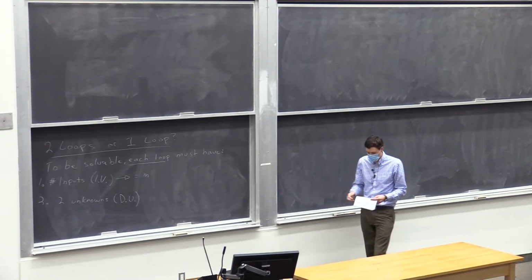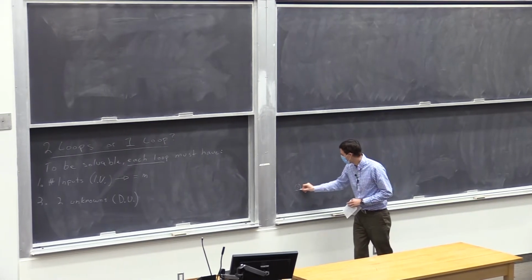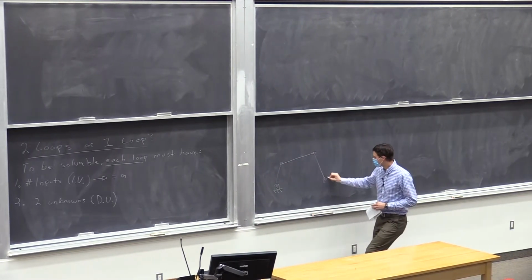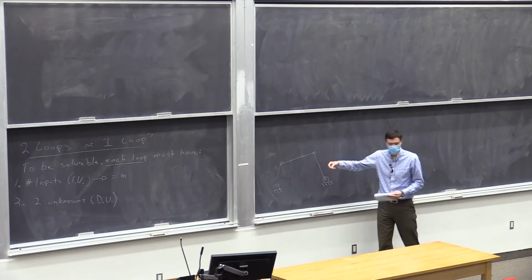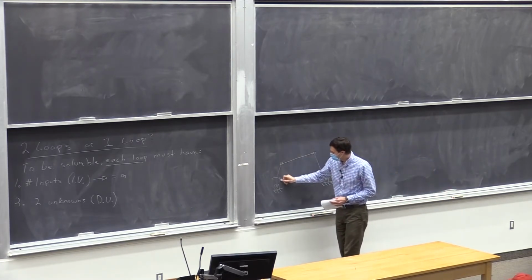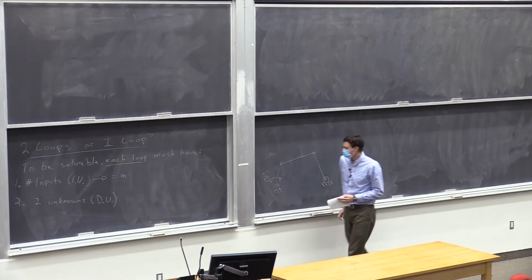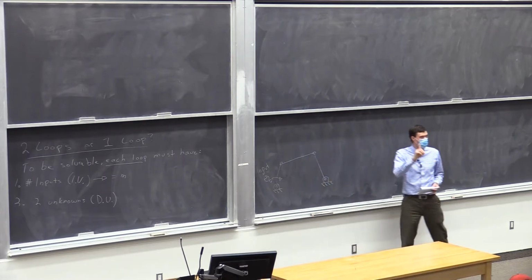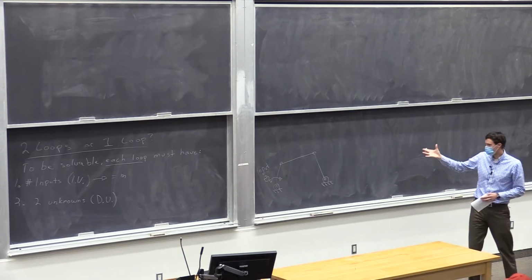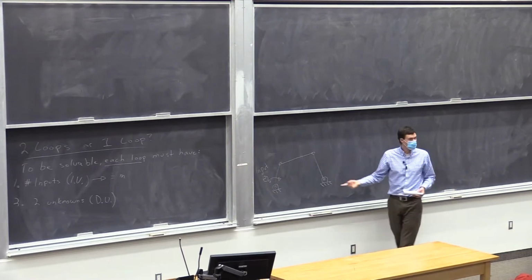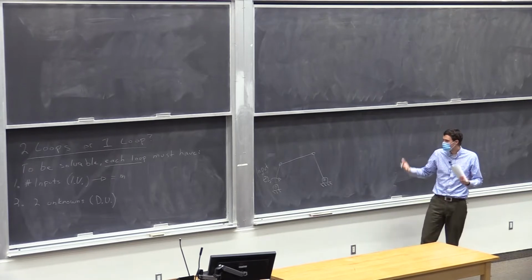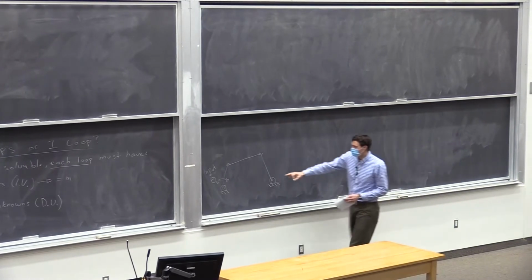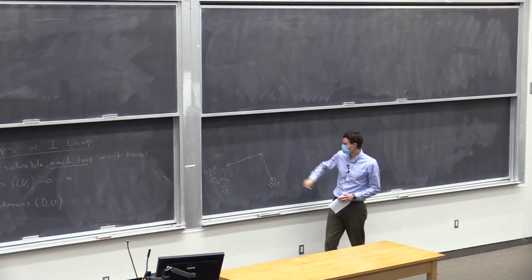So let me give you an example of a mechanism. I'm going to draw a 4-bar with some additional elements to it. And we're not going to solve this one in detail today. So here's our 4-bar. We may say our input here is theta 2 dot. And we know this mechanism has a mobility of 1. So 1 input will do the job. It'll set the state of the mechanism. And we've solved these problems before, although we haven't solved it using a vector loop method; next time we will. Turns out this one is an example where there are 2 solutions. But we're going to ignore that for now.